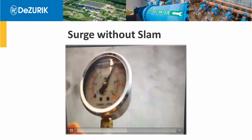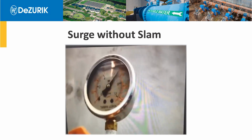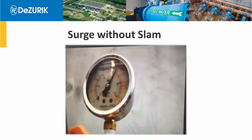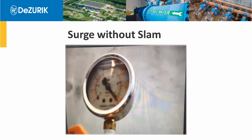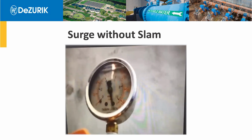Here's a gauge on a discharge header. We've just lost power to our pump. Our check valve was a lever and weight with an air cushion. It closed quietly. We think everything's okay in the pump station, right? Well, we still have our surge pressure, upsurge and downsurge. And if that high pressure portion of the spike is more than what your pipe is designed to withstand,